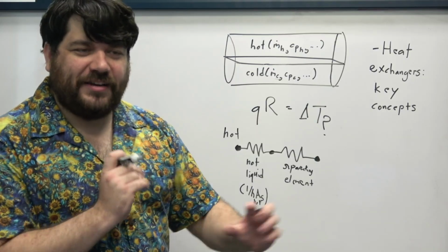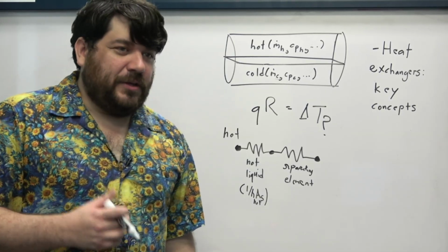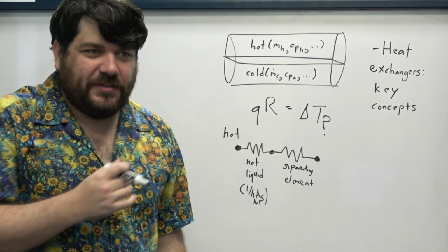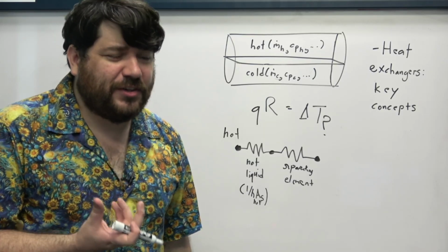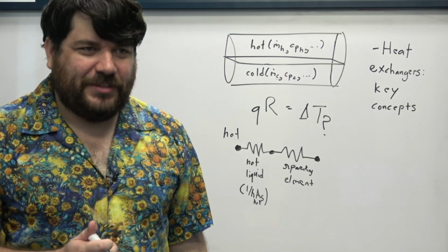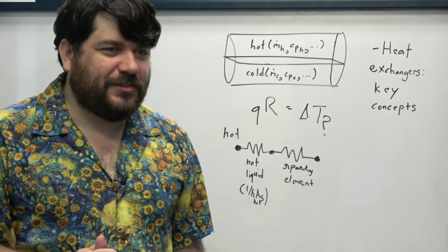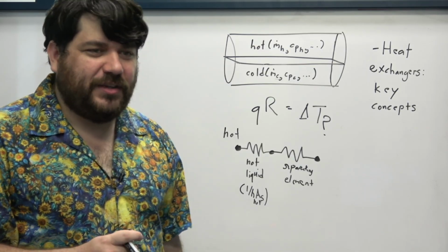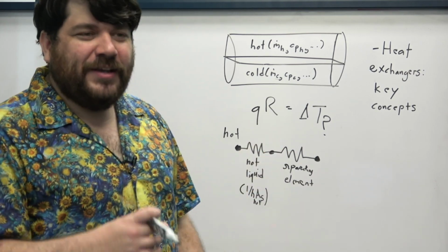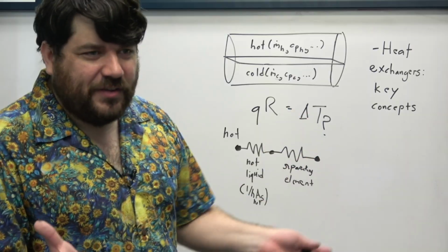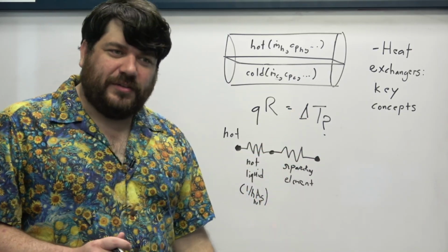You can imagine that if we had a set of concentric tubes, the separating element might be cylindrical. But you can also imagine, as we saw in the example for a heat exchanger before, that the separating element or elements have such an extremely complex dividing geometry that we can't really use expressions for conductive thermal resistances that we've seen before. But nevertheless, this is a conductive thermal resistance. Whatever that number is, whatever the goofy expression is, we know that there's a shape factor associated with it, and that therefore we can find a conductive thermal resistance.